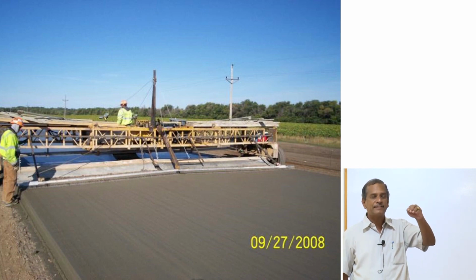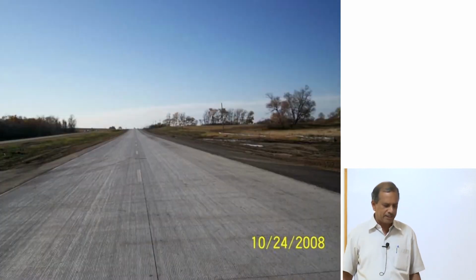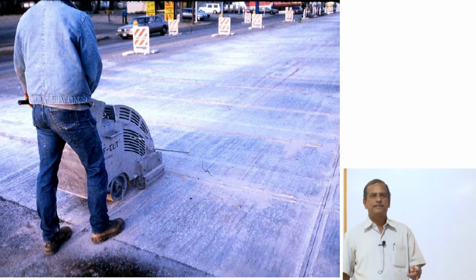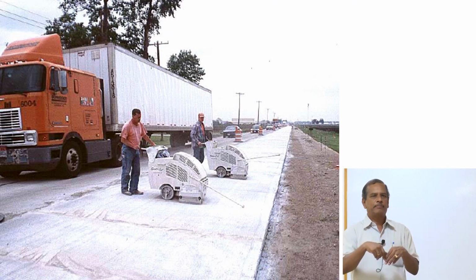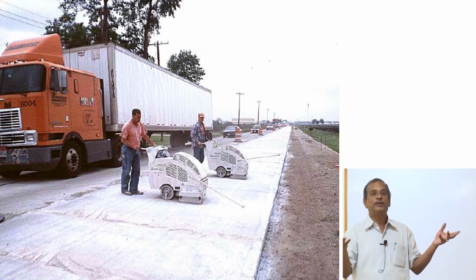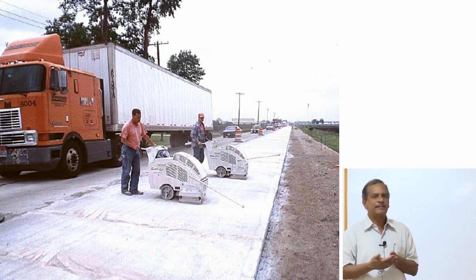But you have to cut this to size to 1/3 depth using cutting machines. So more cutting machines are required if the slab size is very small. So you can have whitetopping on a deteriorated bituminous pavement and forget about the road for 20 to 30 years. So bituminous pavement can also be made sustainable by constructing concrete pavement.